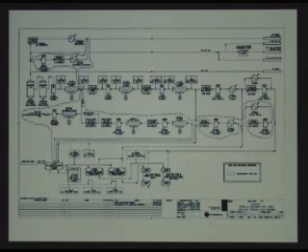Say you've got a plant that has an existing train of compression, and you want to put in a second train in parallel that shares some of the same process equipment. This new train shares every separator, and it shares that discharge cooler. With the existing train operational, if you start up the new train, effectively you've doubled the flow rate being pulled out of the separators, and you doubled the flow rate being pushed through that cooler, none of which were designed for those flow rates.